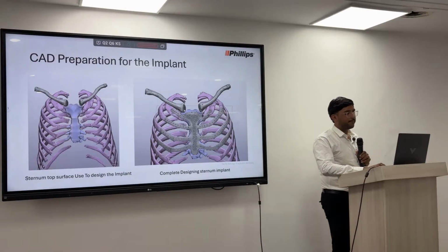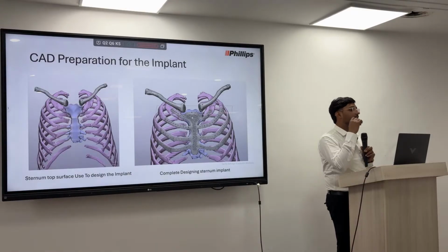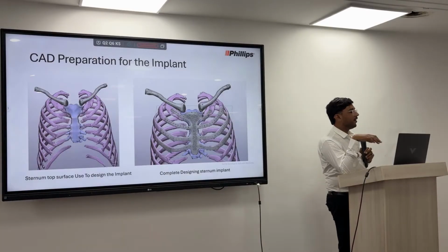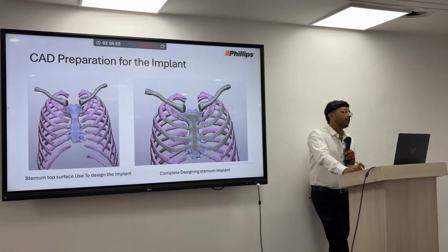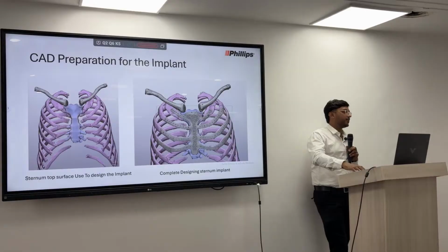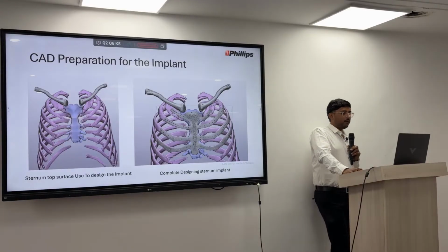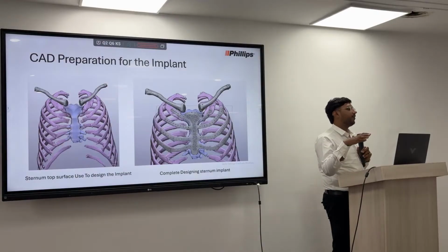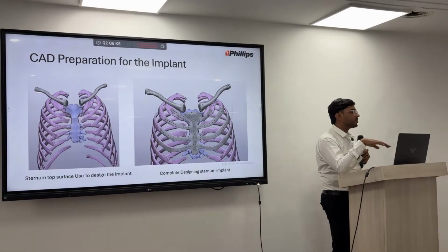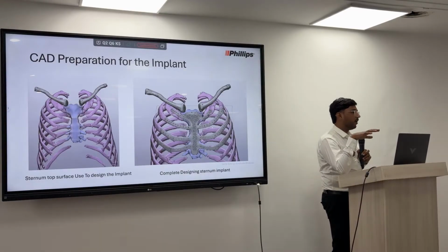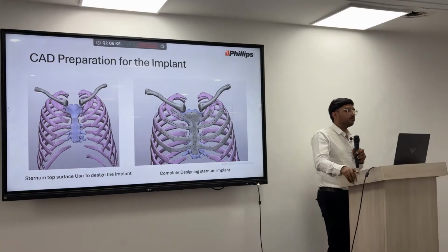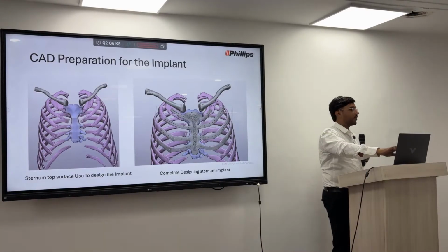So you can see there is a completely different structure over there, because when we started the planning, around 1.2 kgs of material would be consumed. So the doctor said 1.2 kgs is too much weight for the patient, it will not be sustained. Then we used a lattice structure to get 600 grams of material. So the complete implant will be 600 grams only. That is how AM works. If you go with subtractive manufacturing or other manufacturing methods, you can't obtain this kind of lattice structure.